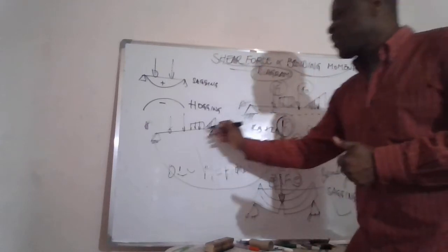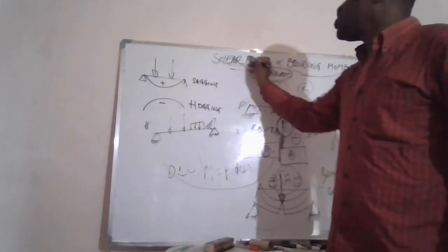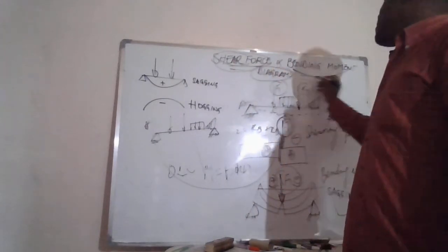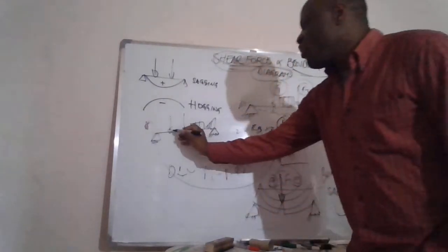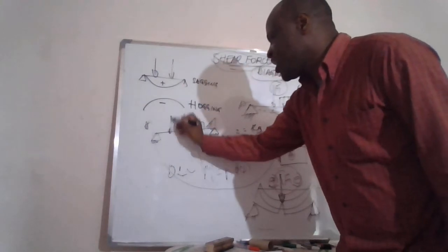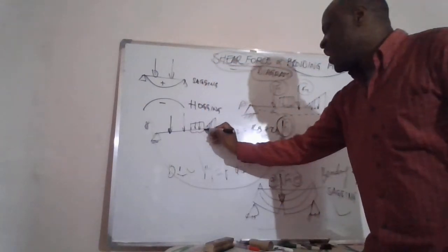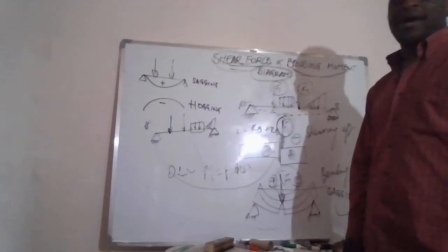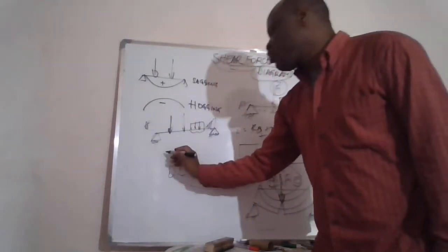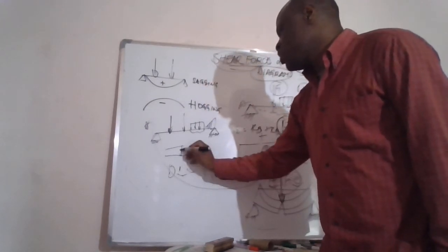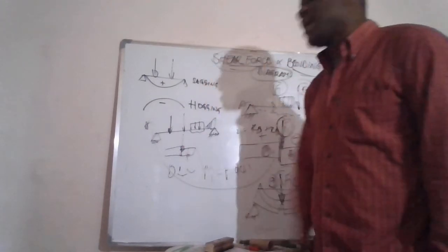And the twin effect will subject a beam either to shearing off and to bending. The shearing off takes place at the cross section where the load is applied, or on the length where the distributed load is applied. And the shearing effect will have a tendency of cutting a beam into two portions due to the effect of the load that is acting.